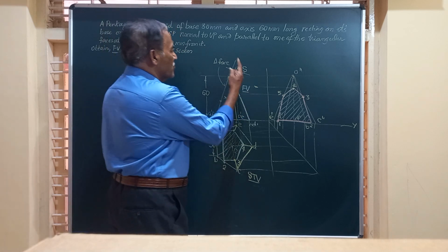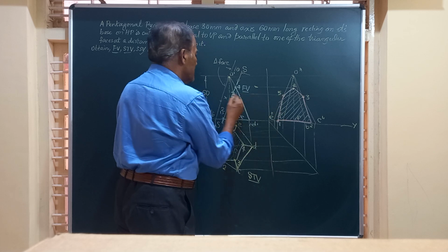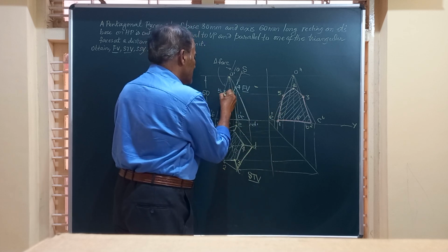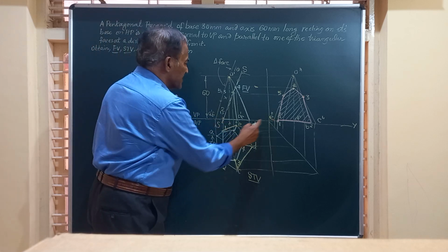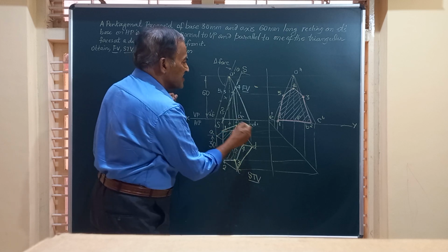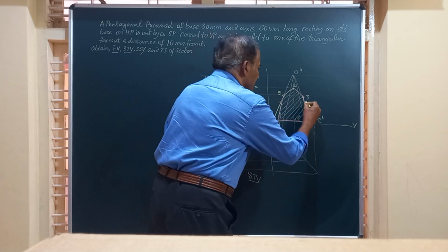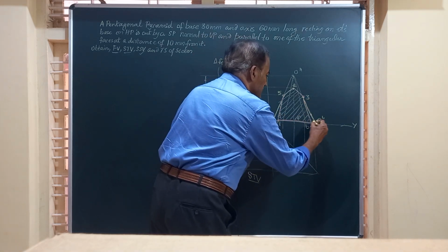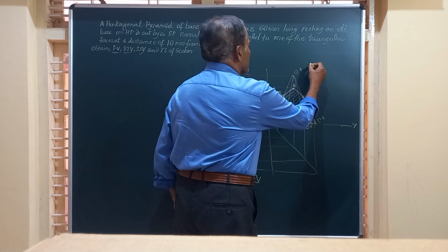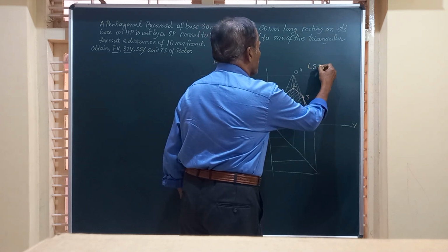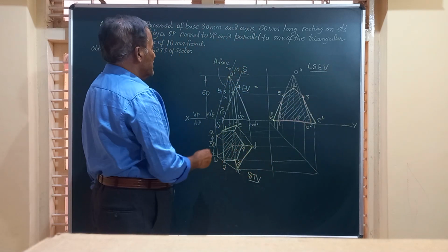Say, friends, the portion above this is removed. So if you want to transfer, you can have this transfer. This is 4, this is 5 comma 3, and this is 1 comma 2 already marked. And friends, here you have to just see whether E is existing or not. E is there, C is there. So I have to show this portion by visible lines, again this portion by visible lines. So this is existing. And friends, this is how we obtain the left sectional end view or SSV, sectional side view. And it is what we call the sectional top view.